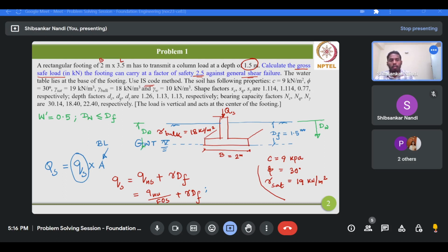Okay, so please keep in mind the reference against which we are measuring the depth of water table. So here it is the ground surface. The datum is ground surface. Now this water table correction factor again would be 1 when this dW is basically greater than or equal to dA plus b.